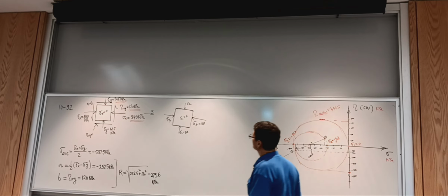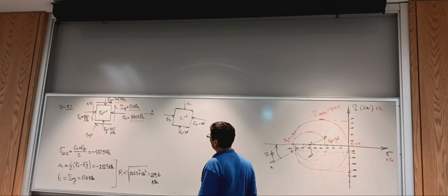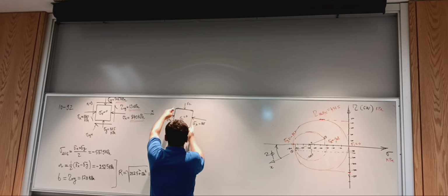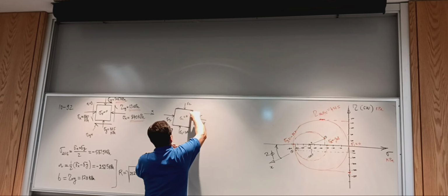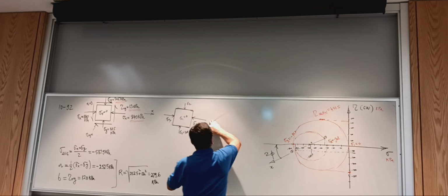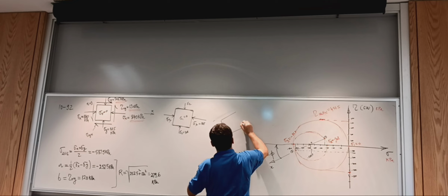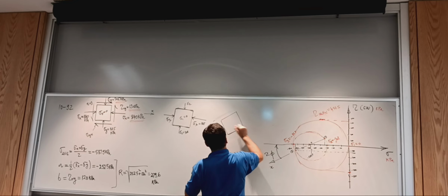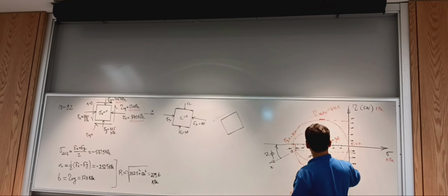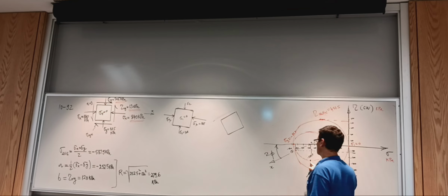Okay, and then to draw the maximum shear stress element, you have to take this and rotate it further 45 or backwards 45. So how will that be? On the circle, I have the x-axis to encounter the tau max, not the true tau max, the tau max on the 2D circle.